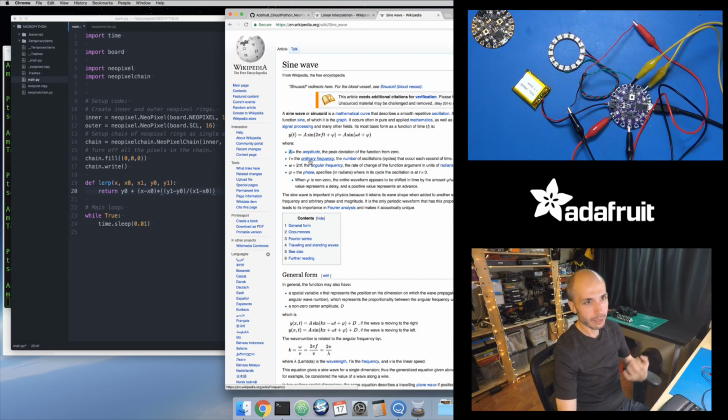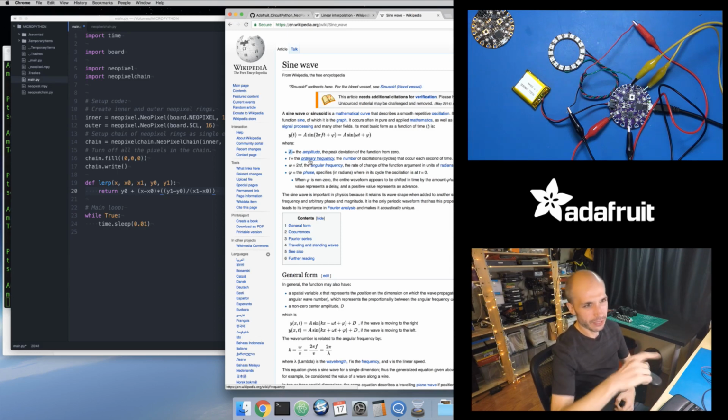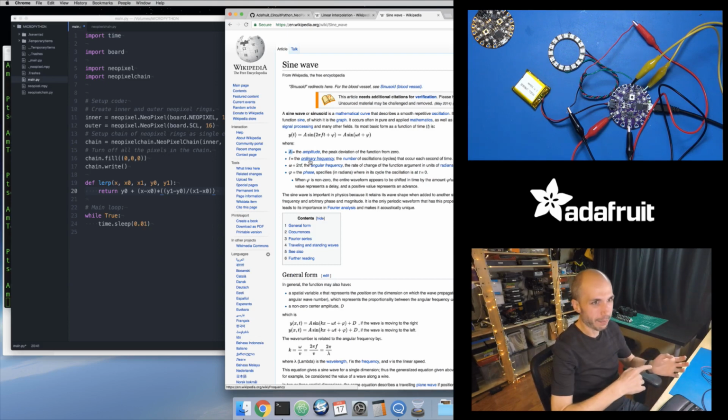So if I use a frequency of 2, it's going to oscillate twice per second, going from 1 to -1 and back up to 1 twice a second. It starts at 0 and goes up to 1, then down to 0, then down to -1, and then back up to 0. Or if you use a cosine function, it's offset in a slightly different phase. It doesn't really matter. The frequency controls how often it goes from 1 to -1.